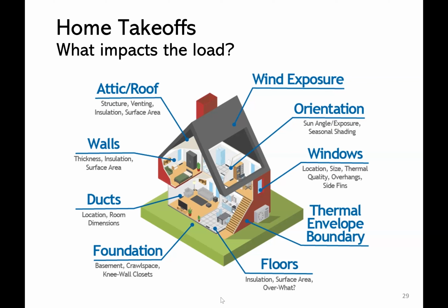And then what about the forced air ducts of the home? Are they located inside the conditioned space or outside the conditioned space? What's the quality of those ducts? Are they sealed tightly, or has the old duct tape dried and peeled and they've become leaky? If they're leaking into the unconditioned space in the attic, that's all conditioned air that's being lost directly to the outside.